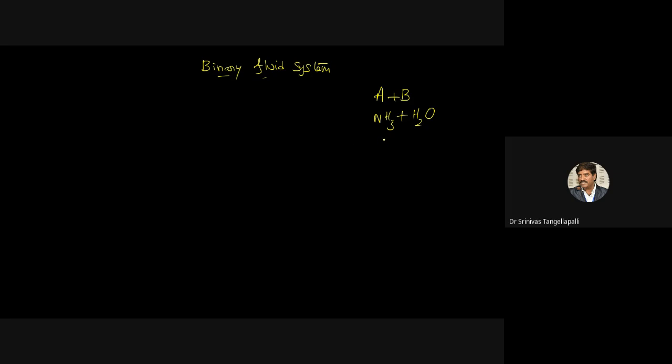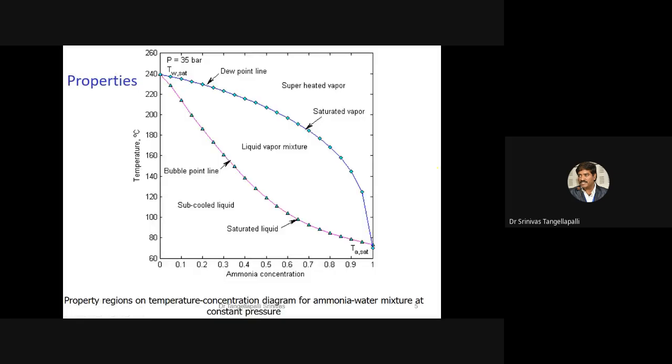Now there are no constraints. Once you add H2O to NH3, there is no constraint on the condenser. As usual, with the ambient temperature you may reject heat, but the amount of H2O should be a weak mixture, actually speaking. More H2O may be required because in Indian climatic conditions the sink temperature, I can say, is 30 to 35 degrees centigrade.